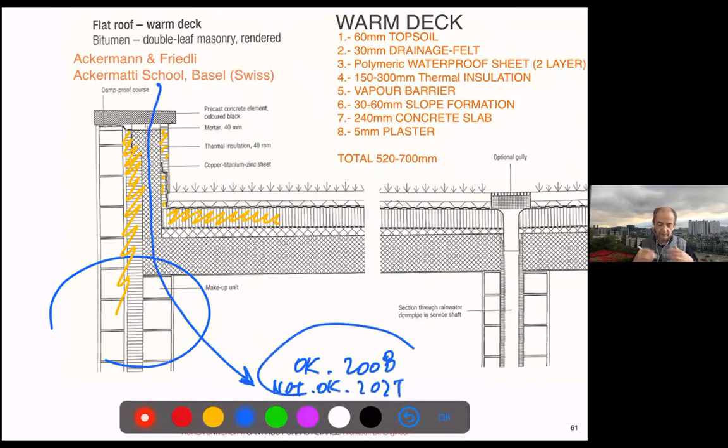So we have to improve our detailing. Same happens with the water coming out. So this pipe will make noise and this is the exterior, right? So you will have heat, so you need to insulate so you don't have that cold water creating condensation problems in those walls and giving noise. So insulation is a weak point, but apart from it, you see the layers.